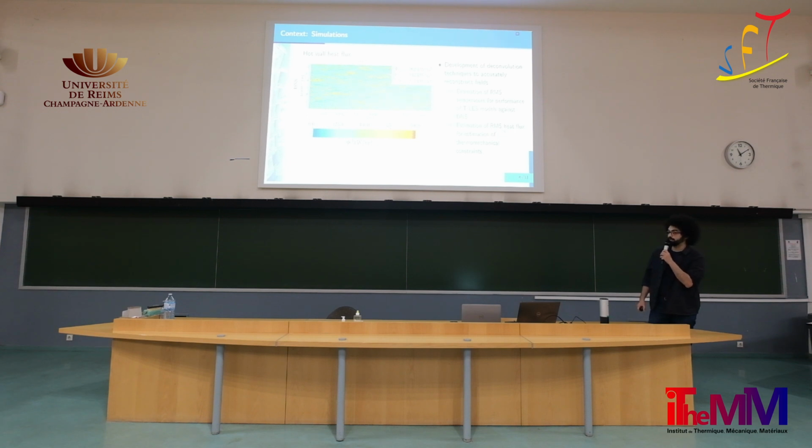It is also necessary to develop these techniques to compare LES fields with DNS, because we do not have a way to compare them if we do not do reconstruction, especially for their RMS, which is a quantity of turbulence inside the flow. And the RMS of the heat flux also gives us a way to simulate the thermomechanical constraints inside the receiver. So these quantities are extremely important.